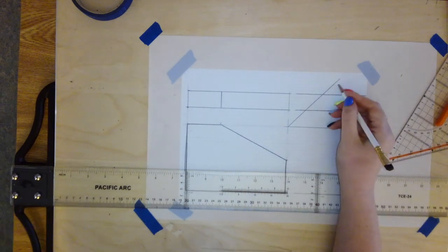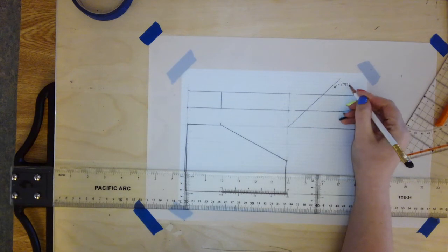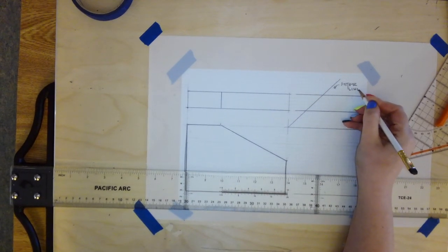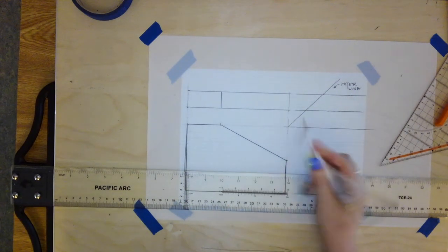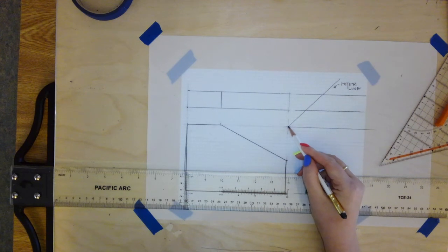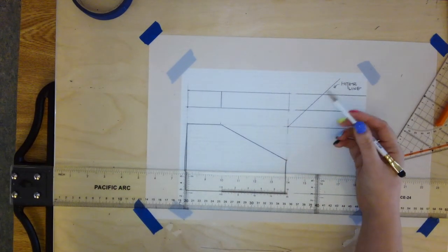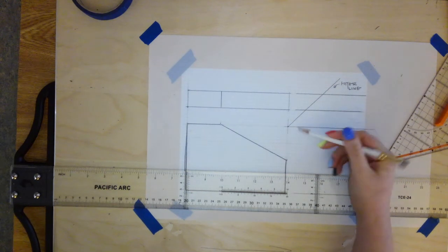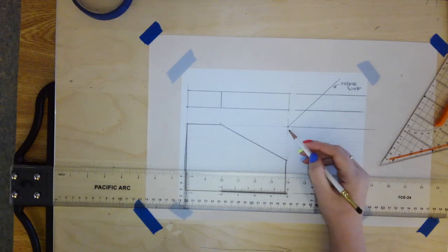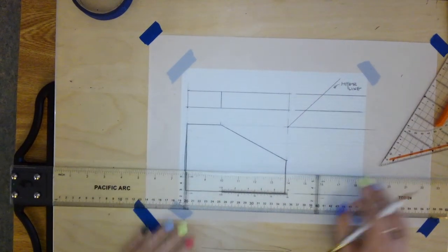So we make our miter line where the top and right side of the front view meet. Even though this isn't on my object at all, that's still where I would project my 45-degree line out. Oftentimes our miter line does sit directly on the side of our object, but in this case it doesn't, because it has just a gap up here.